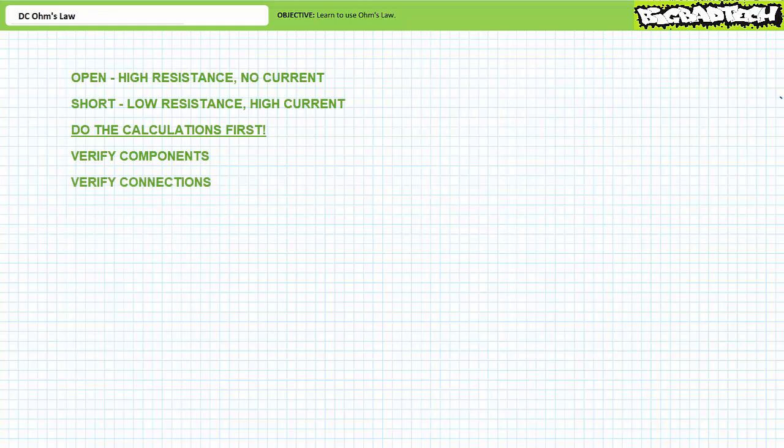Double check the circuit. Make sure it's hooked up as intended. Use colored wires and label the nodes. Look at anything you suspect of being open from all angles, not just the top. Different viewpoints often quickly reveal a missed or off-by-one connection.